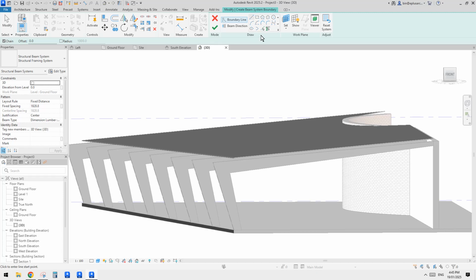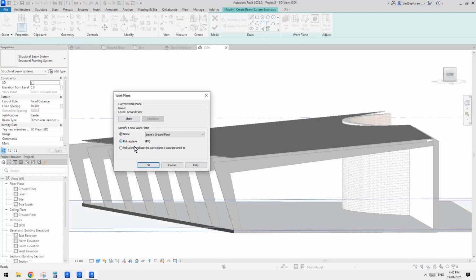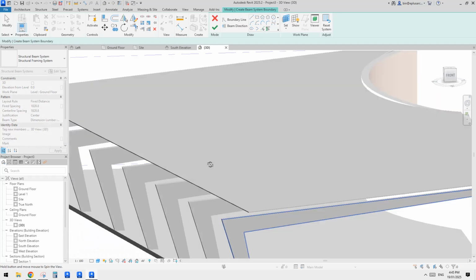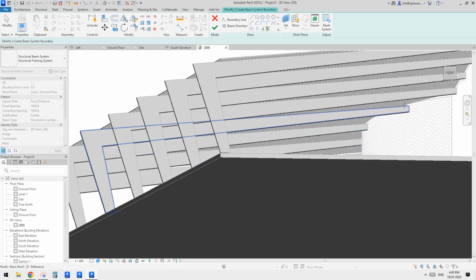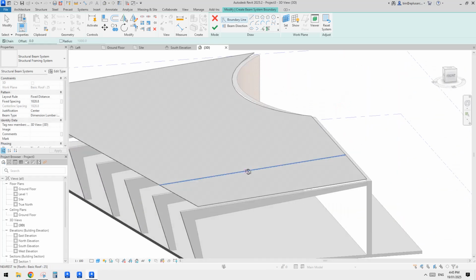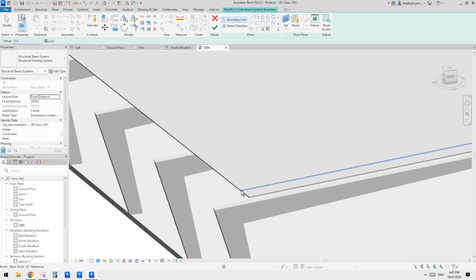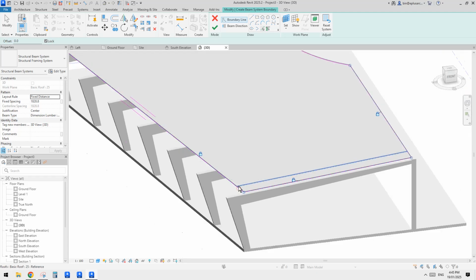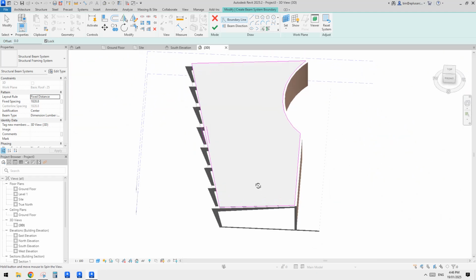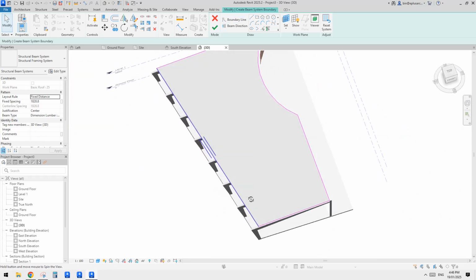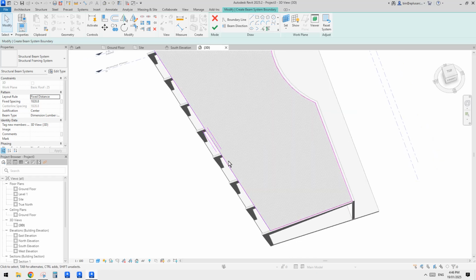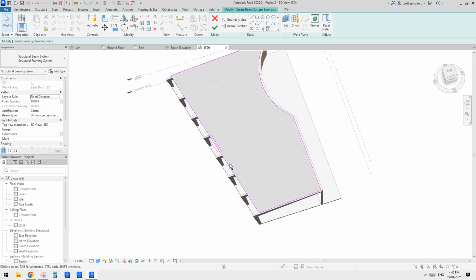So it's very simple. First set work plane. I'll pick the work plane, you can use the underneath of the roof, right? So you can pick that, and then pick line, tab. Oh, it doesn't work. Try again, yeah, it works. Tab, and then pick the whole roof. And for this one, probably the direction shouldn't be this.